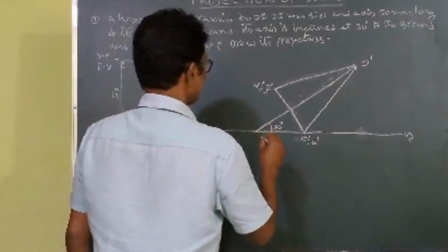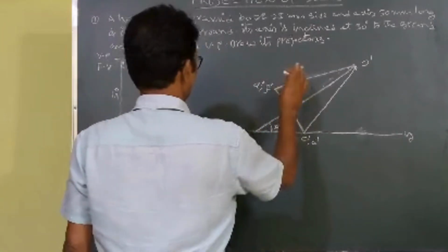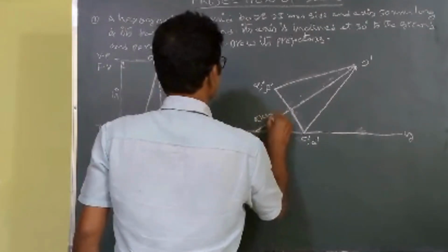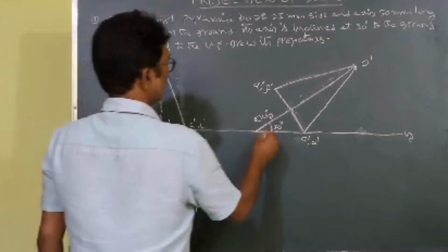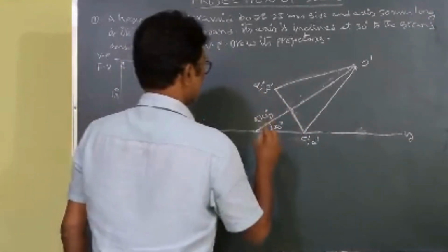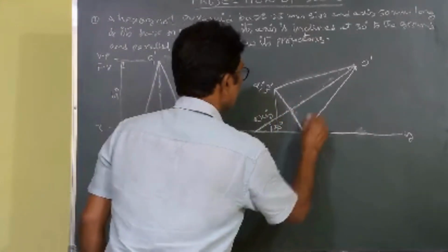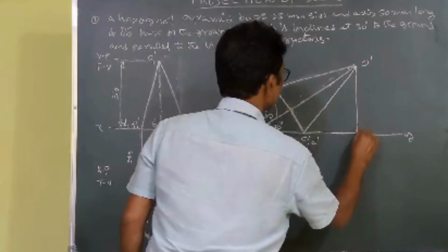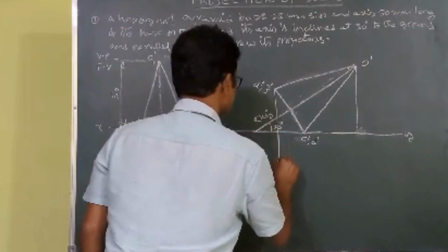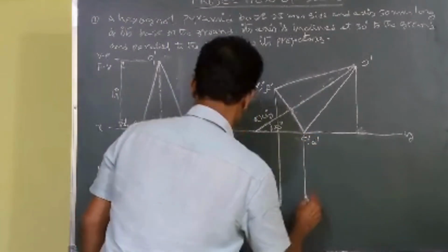Now you draw the projectors from this front view in this position, with the axis making 30 degrees, and reconstruct this diagram in this position. Okay, you draw the projectors once again from here to XY and here to XY line, and they are extended further in the same line, and here also you draw the vertical line.